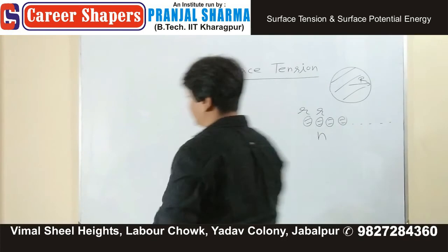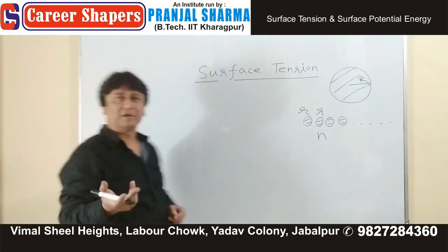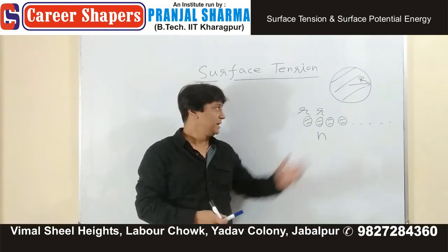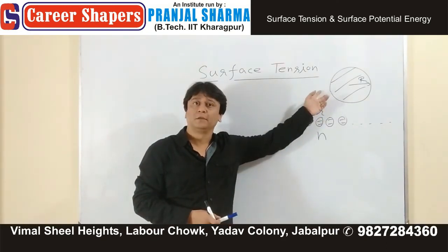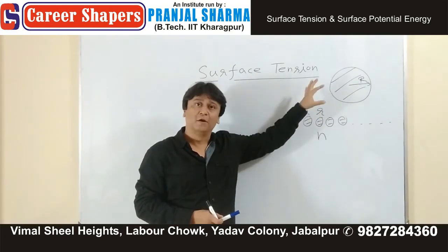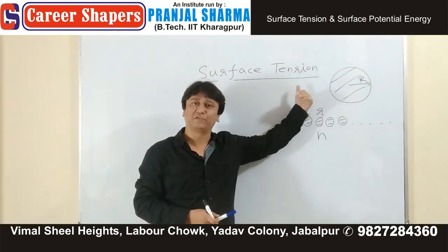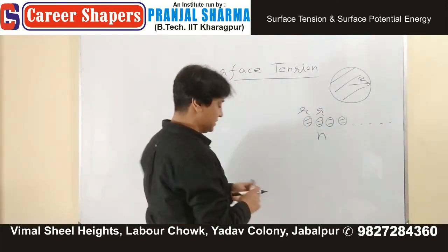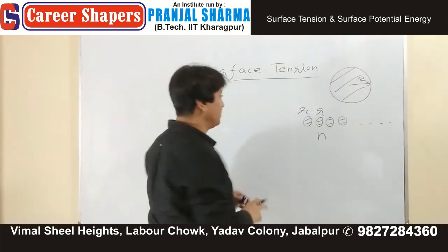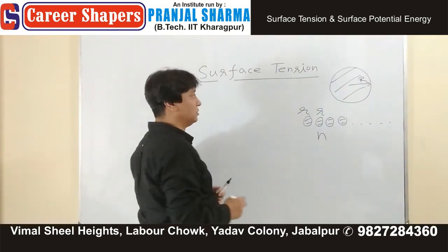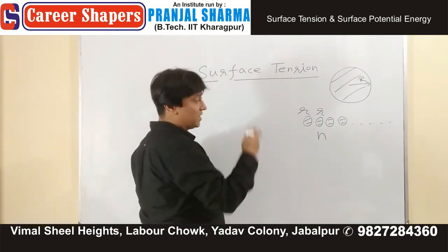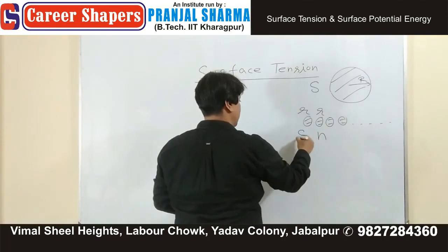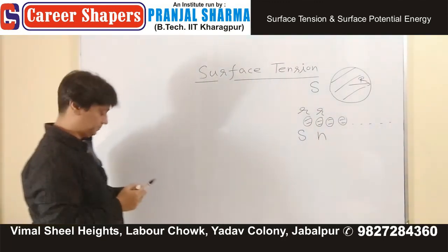Well, only the first answer is correct. It will remain the same. Surface tension depends on what type of liquid it is and the temperature. It doesn't have anything to do with surface profile. It can be any surface. So remember, surface tension will remain the same. This is also a good question for you, in fact. So you can write this as a question also: which one has greater surface tension? Answer is same. Surface tension will remain the same.